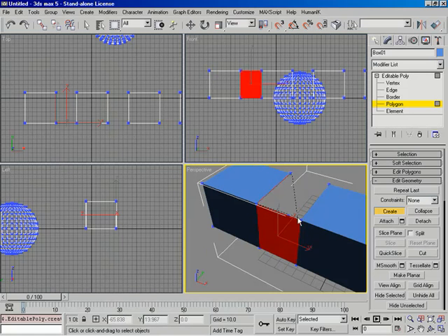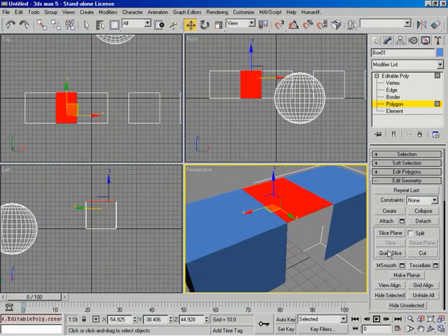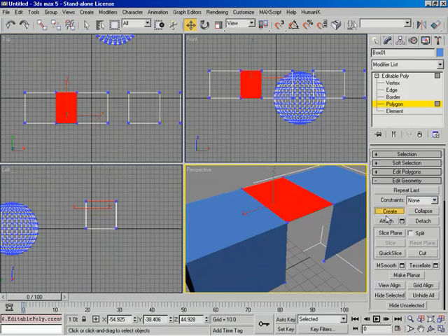Notice how, as I'm going through adding these polygons in... Double-click. I am doing this in a... Oops, I right-clicked one too many. Let's go ahead and come back into this. I'm doing this in a counterclockwise direction. Okay. And why is that? This is so that my normals point outwards from these polygons. In other words, so that I can see them.